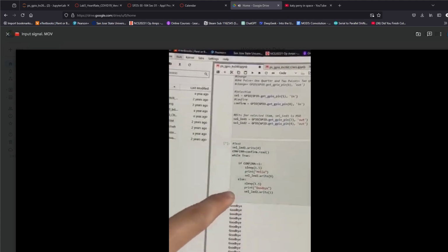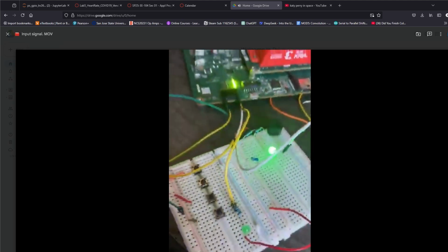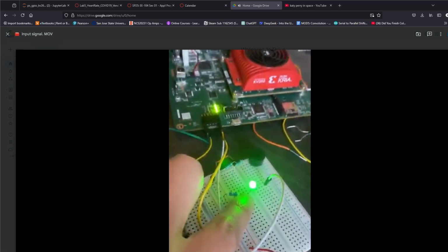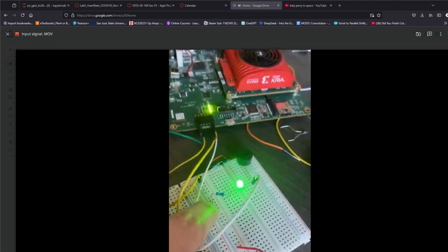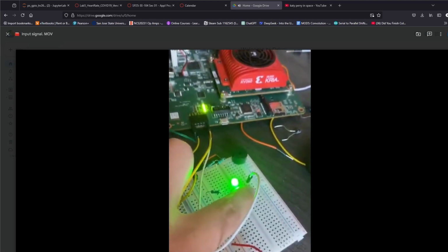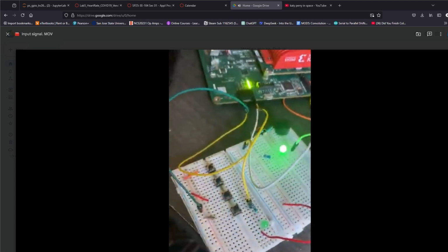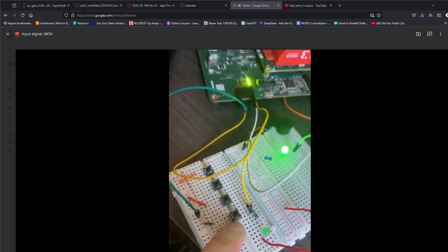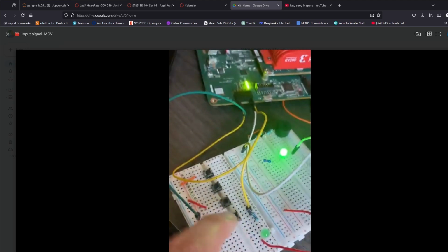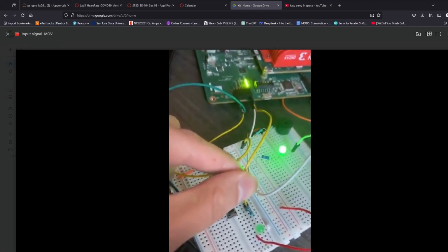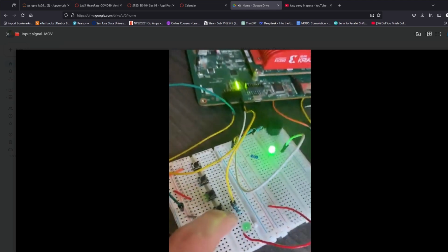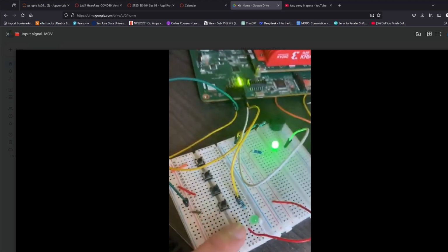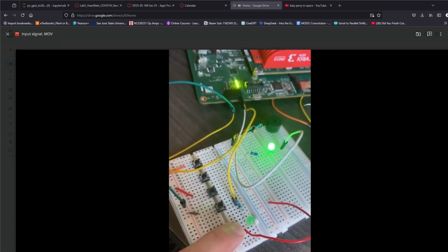being high, right? And in this very simple circuit, this is my output LED. This is going to be ground, of course, and then this is my output signal, right? And on this side, I have VCC connected to my switch here, and then this yellow here is my input signal, okay? And then, of course, from this resistor to this LED to signify that at least I'm getting a signal here that is either high or low, right?